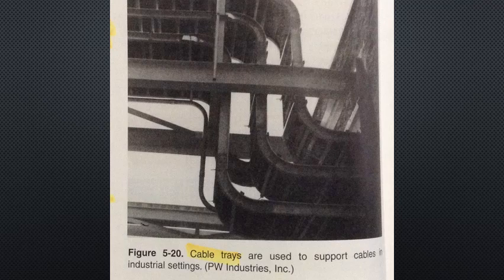This method of wiring is particularly useful and commonly found in laboratories, workshops, stores, schools, and offices, and it is installed exposed on the surface like other surface raceway. It may pass through walls provided there is no receptacle within the partition, and the covers on either side can be easily removed.